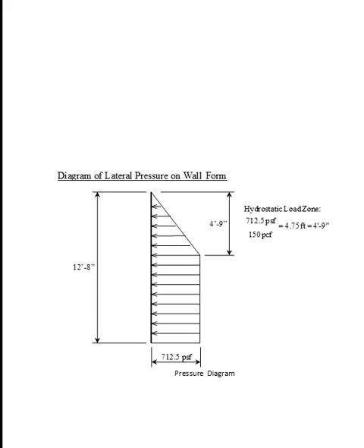Then, as we were talking before, and this is a familiar chart, I think if you had hydraulics or soils, you'll see that this particular loading, and this is the loading we're concerned about, the concrete acts as a fluid, and it applies the pressure out on the sides of the form. So the idea is, if you place the concrete at a slower rate, the concrete starts hardening, and then it slowly, from here on down, starts being directed down instead of off to the sides. 712 is the number we've been calculating, and here it's the pressure on the forms pushing out.